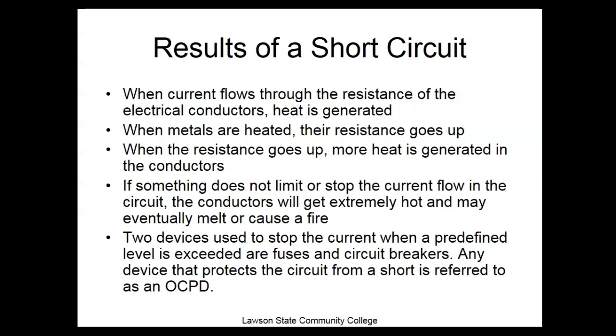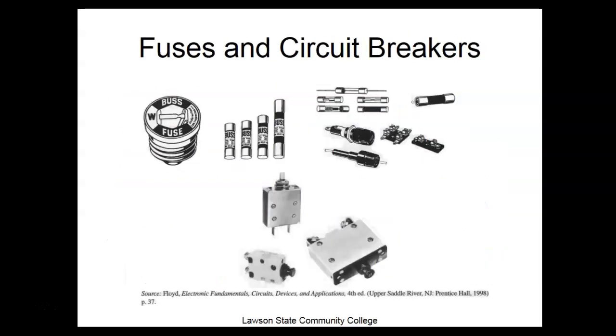Somewhere we had a short circuit, somebody screwed up, they didn't have the right circuit breaker in there. People find out they can replace circuit breakers. I've seen guys do it. You can go to Lowe's and get a 15 amp circuit breaker, and you can get a 20 amp circuit breaker that fits in the same slot. So they have a circuit breaker that pops all the time and they don't look for the problem. They go out and buy a bigger circuit breaker. Or they buy a fuse instead. I've got a 10 amp fuse that keeps blowing. Well, by George, I can buy a 20 amp fuse that fits in the same slot. And then they burn stuff up. That happens all the time, guys.